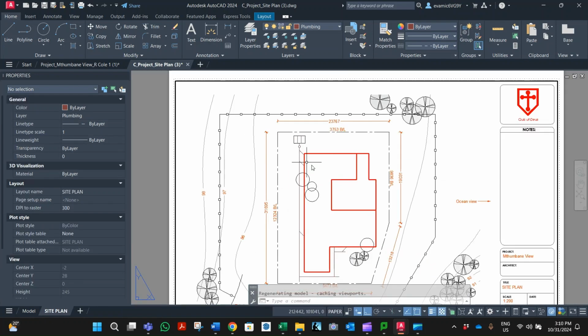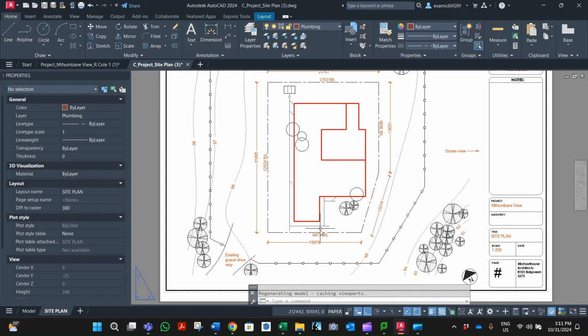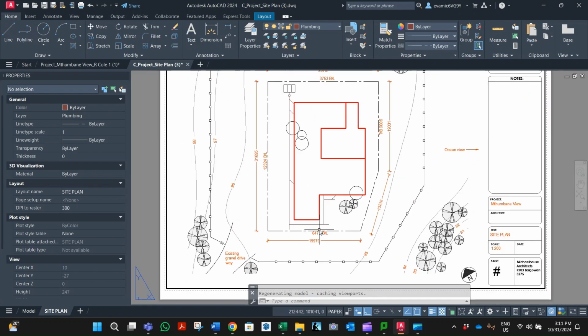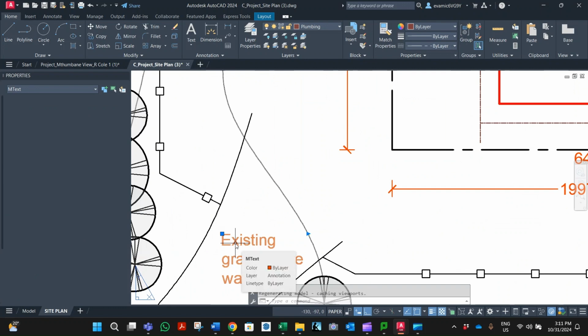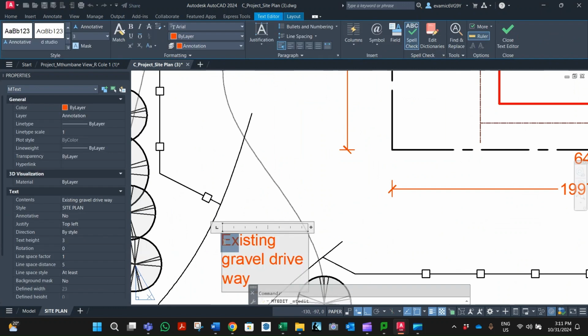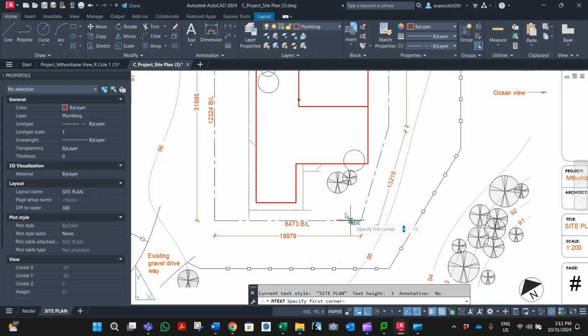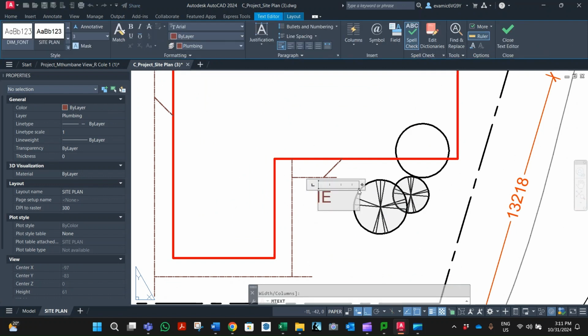You're welcome to label in there, but I'm going to label on top here because we've got everything ready to go. All right, what do we need to label? Inspection eyes, rodding eyes, as well as inspection chambers if we need them. So I'm going to use writing that already exists. In fact, I'll probably take these, just grab those two, Control C. Alternatively, you can go text again and start with your text. We're going to start with inspection eyes, so IEs are what we're going to do.